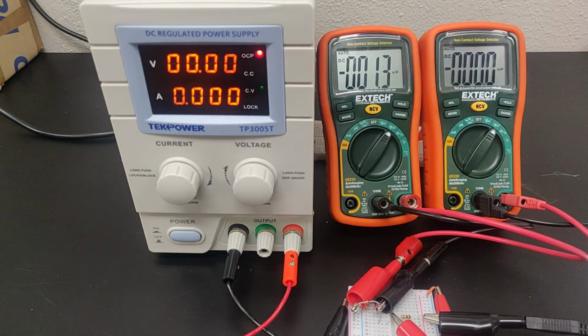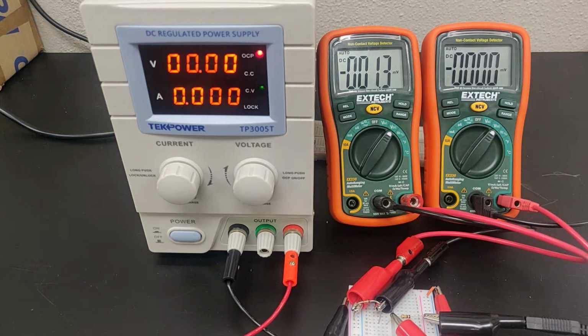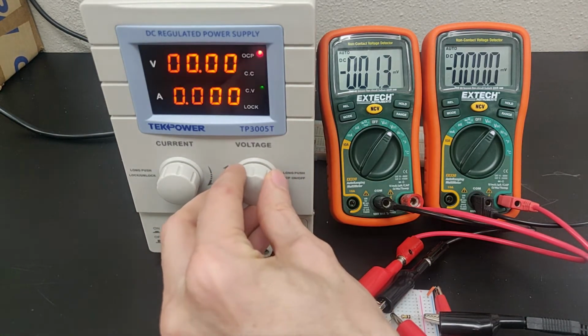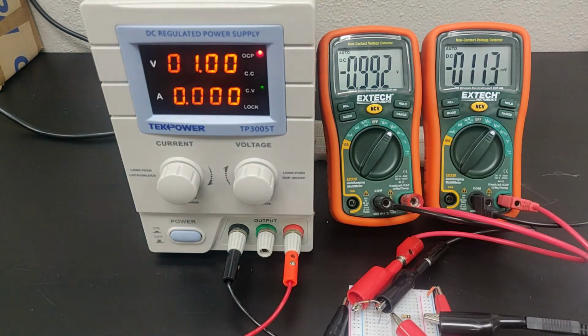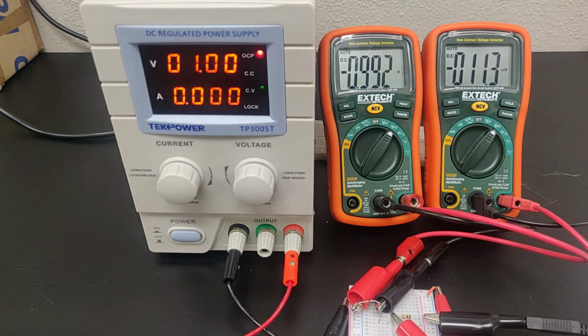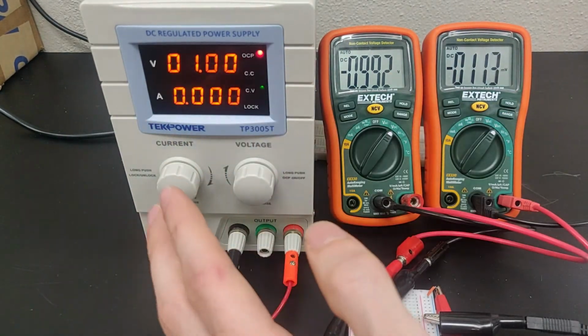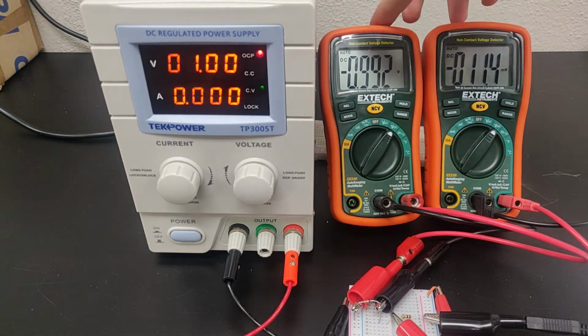So similar setup to last time, where the multimeter on the left is going to be measuring the voltage across the diode. The one on the right is going to be measuring the voltage across the resistor. And right now I do have the 100 kilo ohm resistor in. Looking at the procedure in the lab manual in step 3, it asks us to set the DC power supply to 1 volt and go in steps of 0.5 volts, measuring the voltages across both components, and then getting the current from our resistor using Ohm's law. I will just go through all 18 values, and have you record the voltages here. These are only our important measurements.